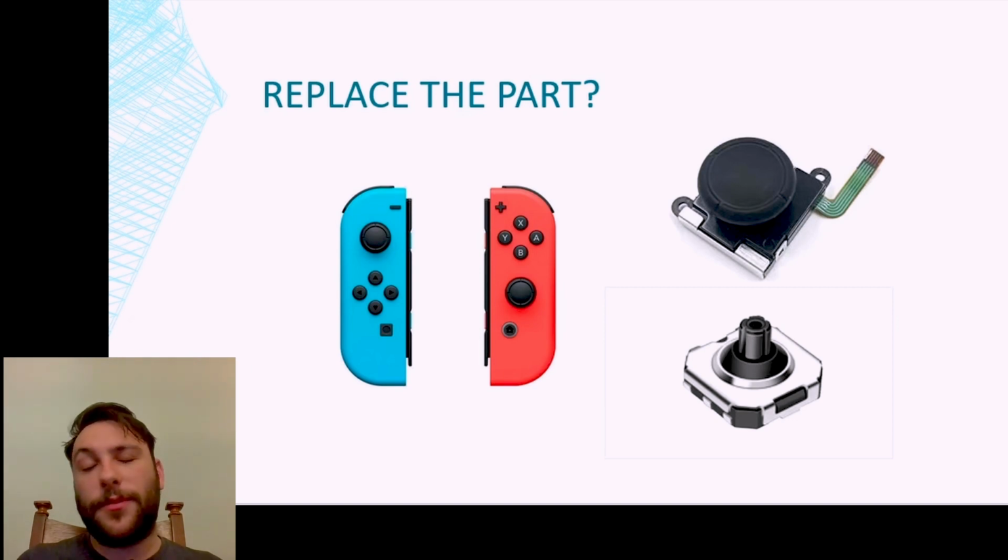And this allows us to figure out pretty much everything we need to know. It gives us the pinouts, the neutral values, the minimum and maximum values, as well as the physical footprint. Everything we need to know in order to find a like replacement. So from there, we can read the data sheets of similar components and find one that works. So we were able to take the problem that we had, use reverse engineering to figure out everything we need to know for the design requirements for a replacement component, and find one that works.